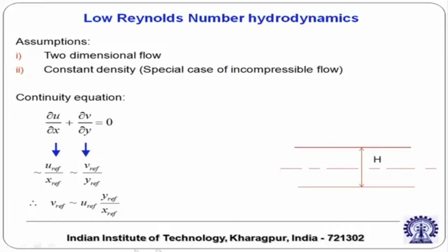We made an important comment that if the vertical direction is the y direction, then the length scale along y is h, but the length scale along x may be the total length of the channel or it may be even less than that, depending on whether there are characteristic changes taking place over shorter distances.